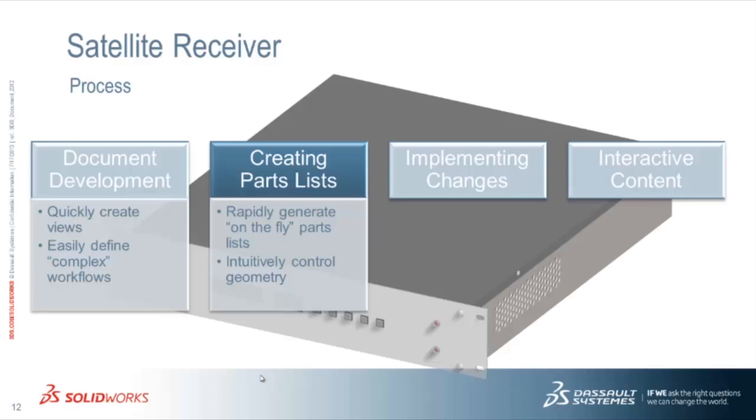So if we jump back into this, the idea is that you're able to rapidly generate these on-the-fly parts lists that just pertain to a given step. Lots of times you have a list of the parts for each step, and each step needs a different parts list with different BOM IDs and different callouts. It's really easy to generate this on the fly rather than trying to manipulate some full BOM complex tables.